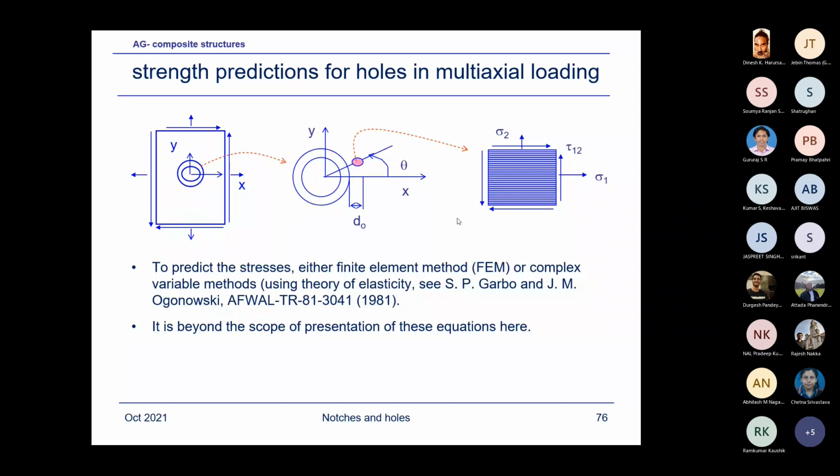Although in this report they considered only the tension or compression characteristic dimension, in general we would consider the calibration of the characteristic dimension for various types of loadings, like tension, compression, bending, open hole, filled hole, and then utilize that, like we did for the bearing. Bearing also is the same thing for bolted joints, using the characteristic dimension, where we determine it for various types of loading.